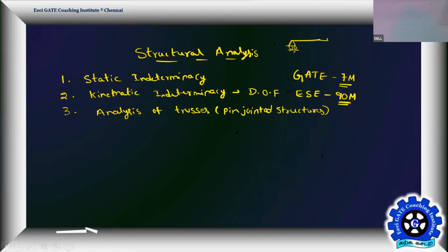Analysis means finding out the unknown quantities. So if you are able to find all the unknown quantities in a structure, then we can say that the analysis is completed. Suppose, for example, you are given a simply supported beam and you are asked to analyze it. What is the meaning of analysis of a simply supported beam? That means you have to find out the reactions, the reactive forces. If you are able to find the reactions, and the maximum bending moment and maximum shear force, then we can say that our analysis is completed.